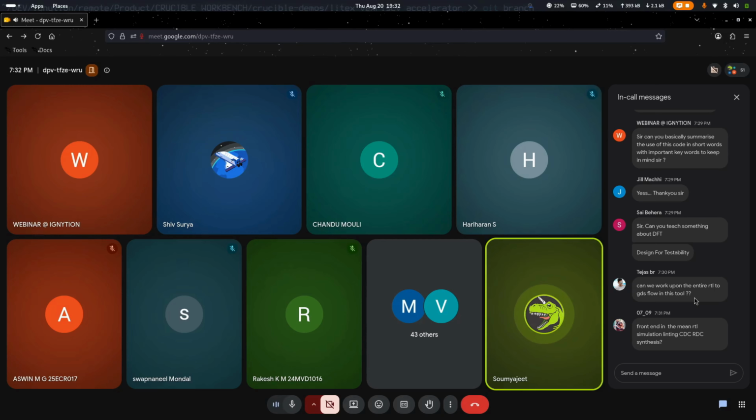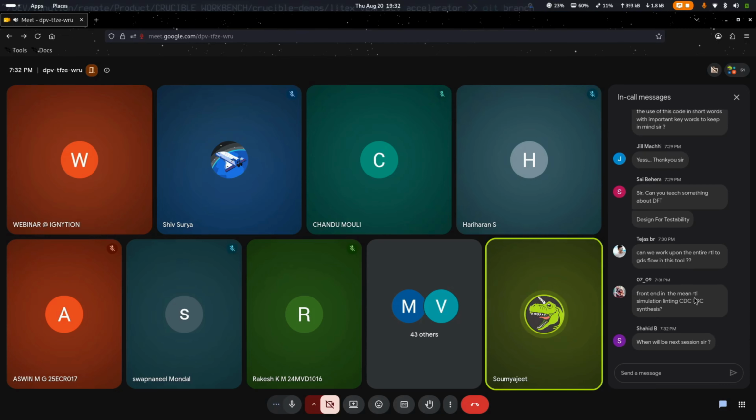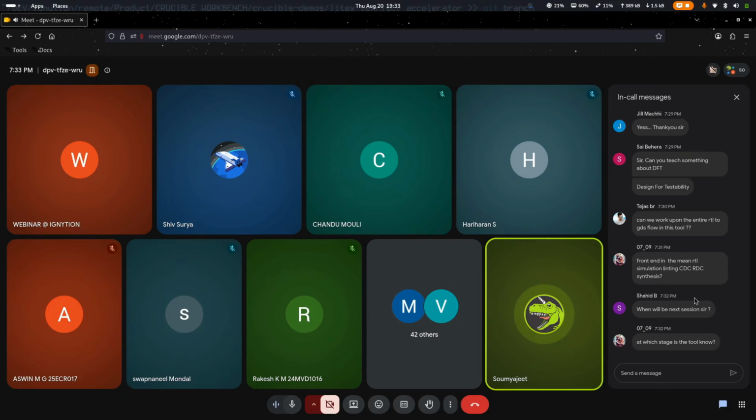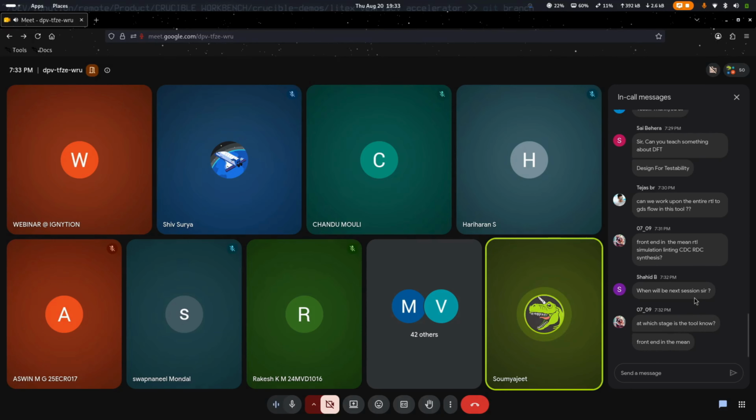logic design part where you write the logic implementation for it and verify whether your logic is sound or not, whether what you started with in your initial assumption coming from the specifications, are they meeting or not. Once you are happy with your logic, once you are confident with your logic, you go ahead and implement or realize that logic into actual circuitry. So that whole second part is called the back end or physical design, where you take the logic which already works but now you have to actually create the chip. So the CDC and all these things, simulation, linting, the linting comes before, but CDC and LVS, DRC, synthesis, these are part of the PD flow.